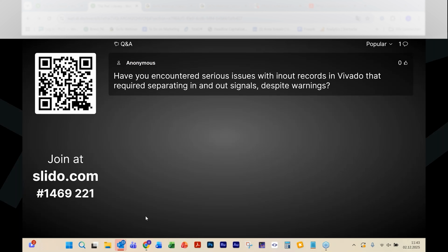And that's the main reason behind it. This technique of splitting records into two parts is also called the Aeroflex-Gaisler method because they came up with it. They are known for their LEON SPARC implementation. And this was also one of the driving factors in VHDL 2019 to implement mode views. So there we have an overlay on records defining, for each individual element inside of the record, the direction, if it's an in or an out.